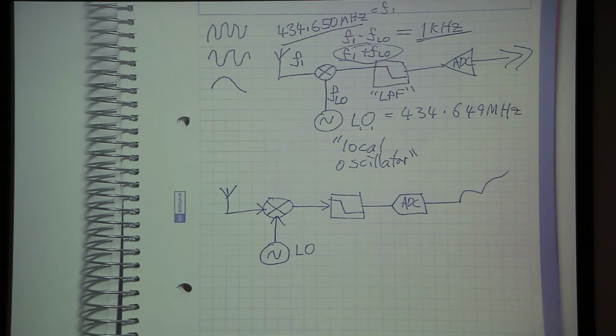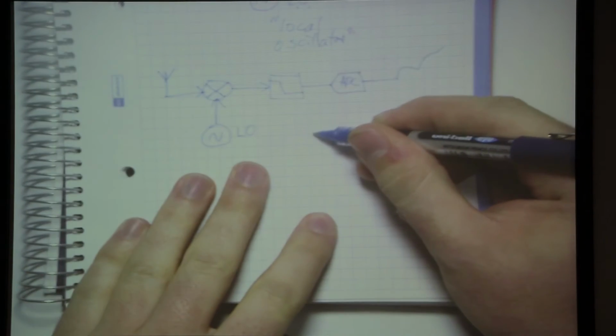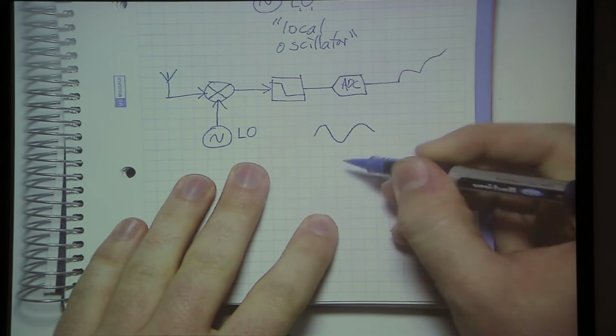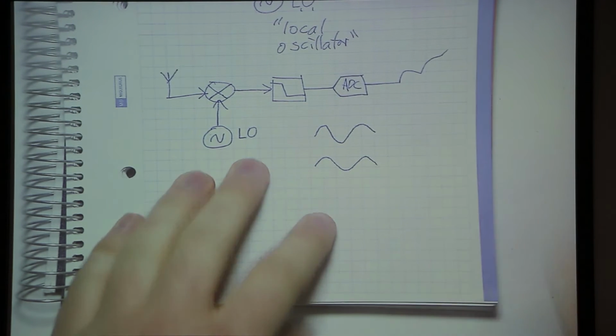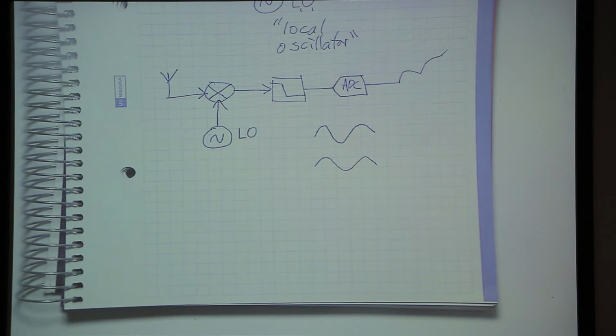This complicates matters, A, because negative frequencies aren't something you usually expect to come across in day-to-day life, and more importantly, B, because they are indistinguishable in this setup from a positive version of a frequency. For example, if you just had some wave at this frequency, the negative frequency really looks the same. So you get 1 kilohertz out just as before. This is a problem if you want to know which frequency your signal actually was. Right now you can't distinguish them, and for various other reasons this will mess things up. So we want to somehow find a difference between this positive and negative frequency.